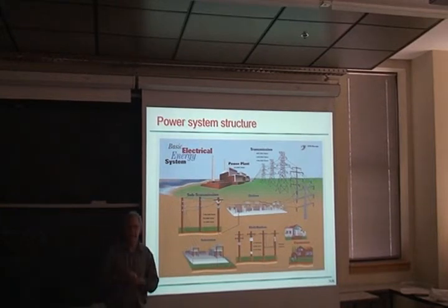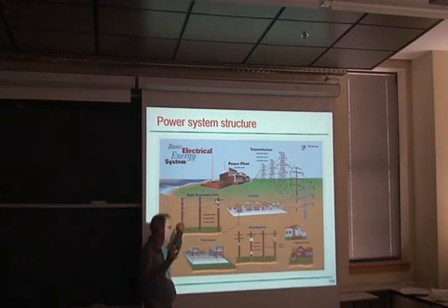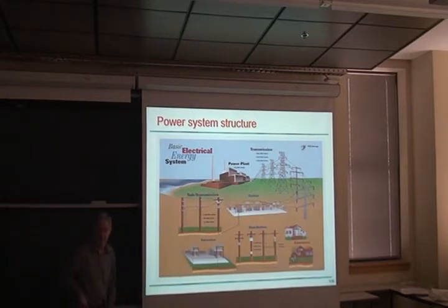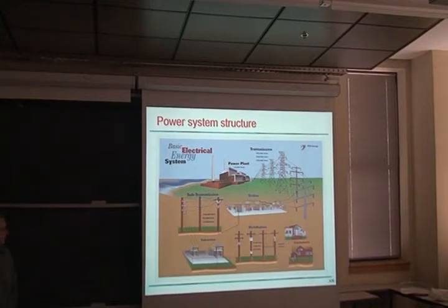When you move to Michigan, there's a lot of work going on in terms of putting wind into the thumb area, and a lot of that wind will go in at the 40 kV level. That's the existing infrastructure, so it's using that existing infrastructure. It's actually too much wind for that existing infrastructure, and so it will create all sorts of voltage control problems, which make for a really interesting and rich research field.